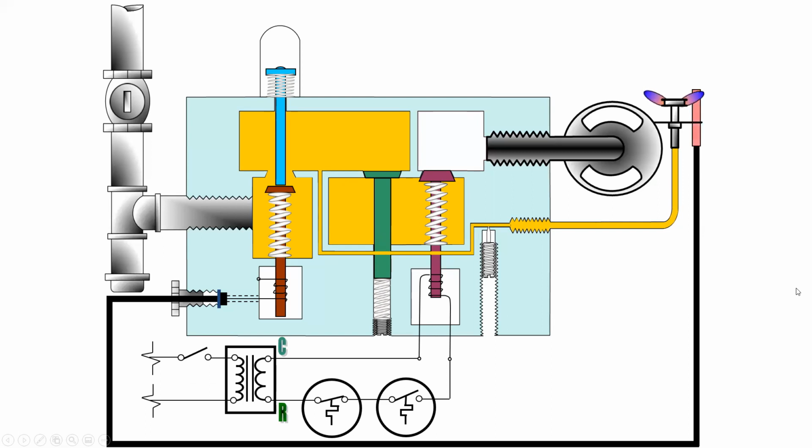Now that we've lit the pilot burner, we still have our finger pressing down on this valve. Eventually, the thermocouple is going to reach such a temperature that it creates enough voltage that the electromagnet will hold this valve in the down position, or open. I can now release my finger from that manual push, and the pilot burner should stay lit. And again, the reason for that is because the voltage generated by the thermocouple is enough to simply hold the plunger in, not enough to draw it down from its upward position.